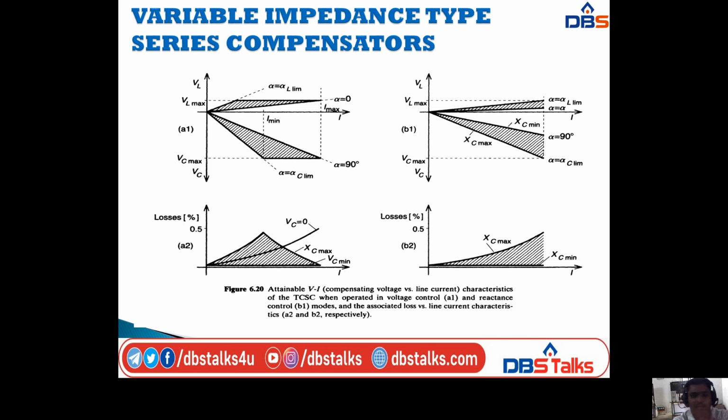Okay, so these four diagrams give the attainable VI characteristics of the TCSC when operated in voltage control and reactance control modes, and the associated loss versus line current characteristics. That is, A1 and B1 give the associated compensating voltage versus line current characteristics, that is, VI characteristics when operated in voltage and reactance control, and A2 and B2 give the associated loss versus line current characteristics.